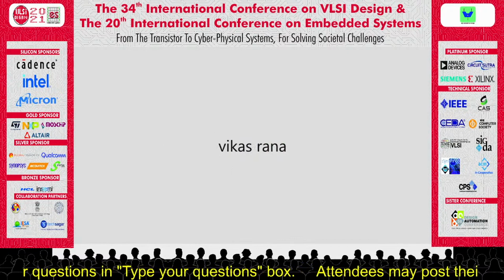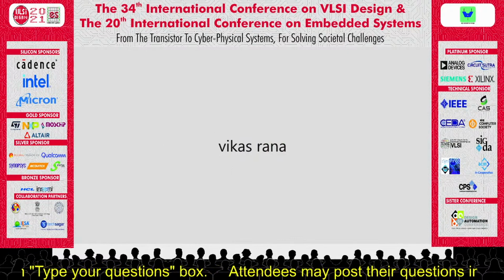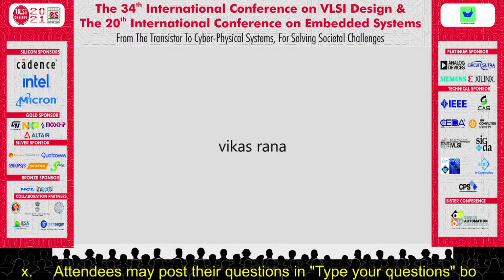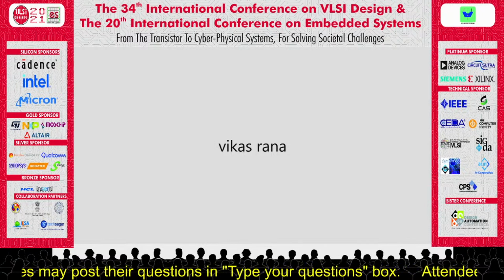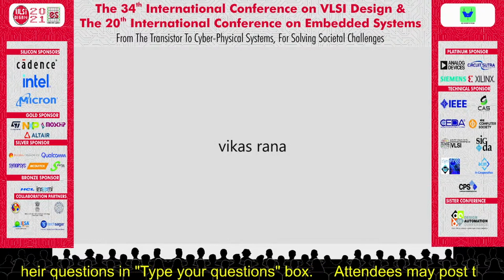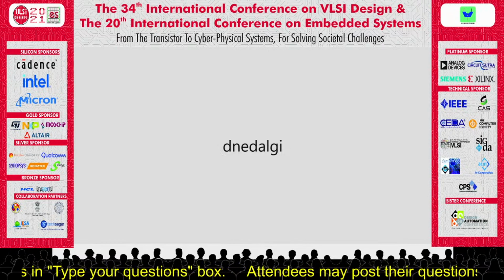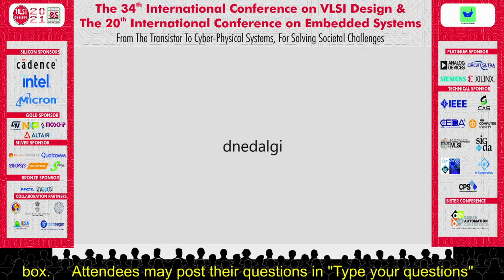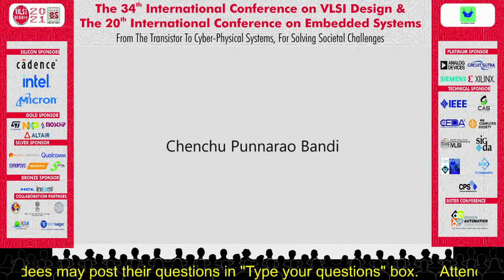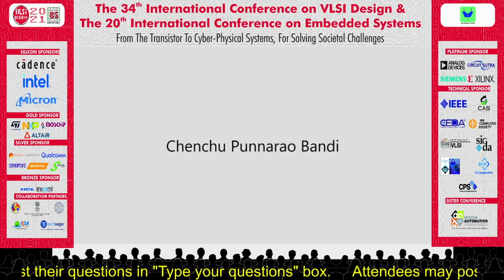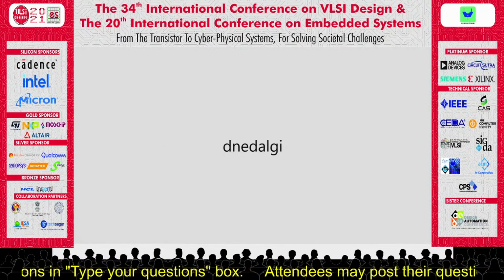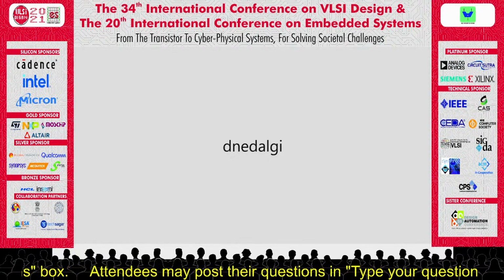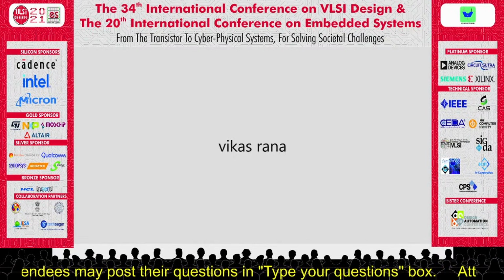Sorry, I have one question. This is Vikas. Sure. Go ahead, please. How are the bulks of PMOS and NMOS transistors managed? Are they made in conventional CMOS technologies, or do you need some triple well technology for it? No, NMOS devices in this particular case are normal, not triple well. PMOSs, all of them are connected to 2 VDD, so that is also visible. But PMOS is possible within the same technology, but we didn't do those variations because the well was able to handle up to 2 VDD. That's why we didn't manipulate that part of it.